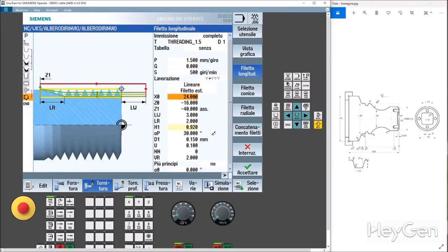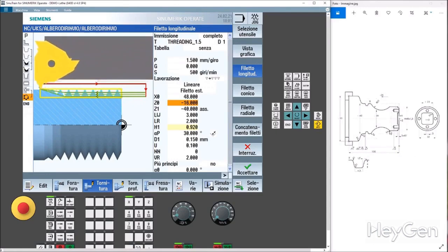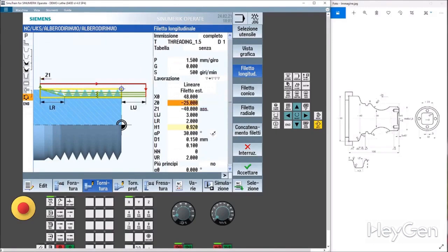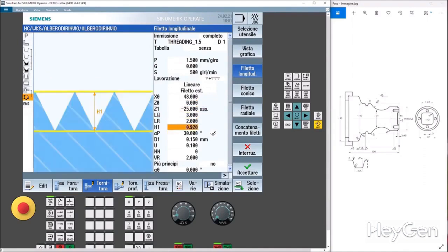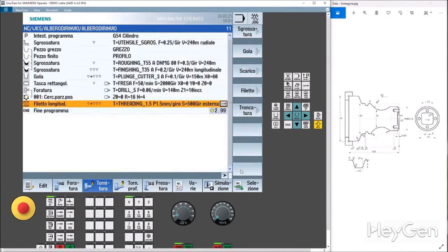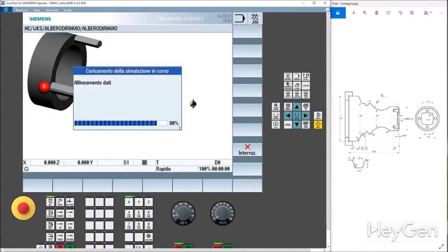Let's start by carefully giving it mainly our machining points. So, 48, length. In this case, we have to estimate a bit. Otherwise, we could go read the program because you see that it doesn't show it here. So we set it to -25 and then we'll see if we need to extend it. Sorry, this is the initial Z. And this is the length, Z25. Safety distance, exit distance, thread depth, attack angle, increment. Excess material for the finishing pass. We accept it, and we're good to go.